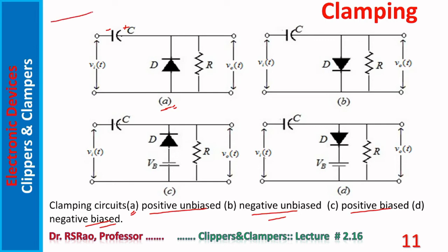If the input signal is assumed to be sinusoidal, then the voltage to which the capacitor is charged is Vm, the amplitude of the signal. After that, the diode goes to the non-conducting state forever and the output voltage is the input voltage and the voltage across the capacitor, that combination, after taking proper signs into account.